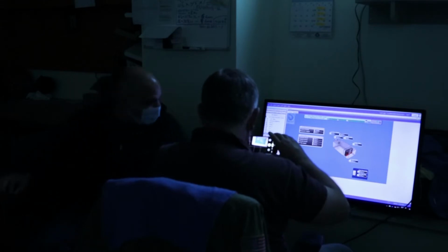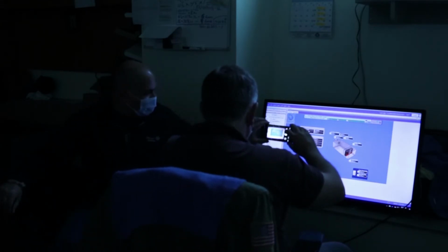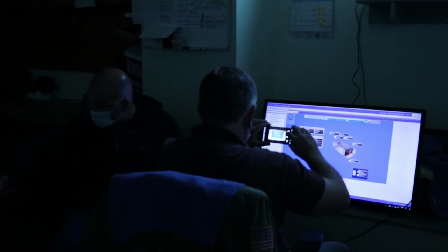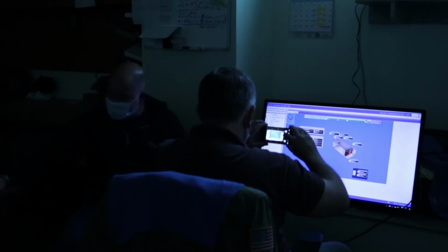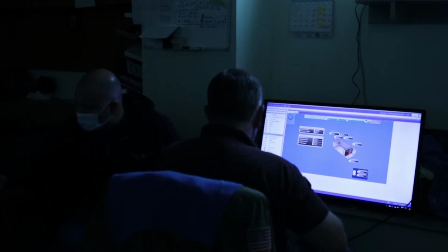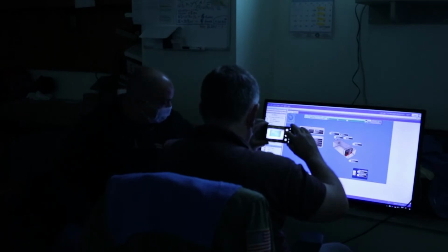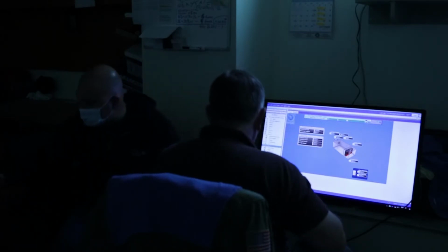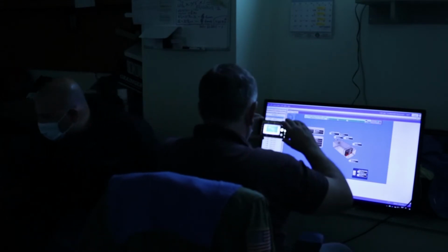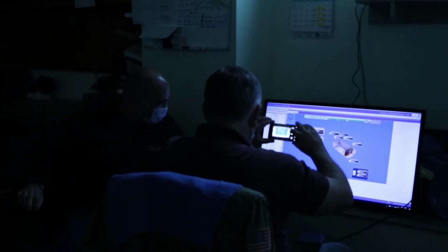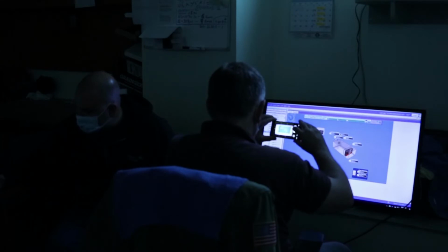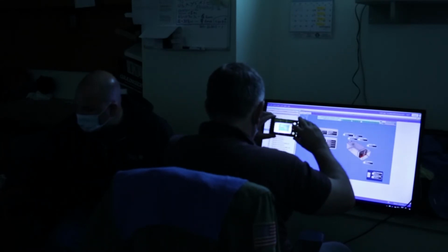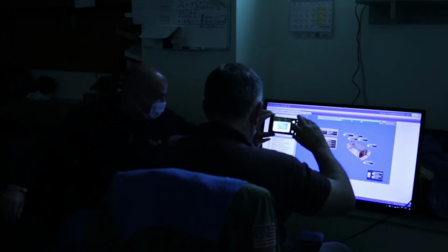Right, we go over to the tree. Now I came over to the tree, and I'm at NAE 5. I'm going to open that up. Now I'm at FC2, because there are 2 buses where there are devices. Now I'm going to open that up and look for the VAV that I want, which is 1510. There's the VAV I want, 1510. We'll bring that up and center it. Now I'm going to open this up and look for the point, which is the zone temperature. So there's the point itself.